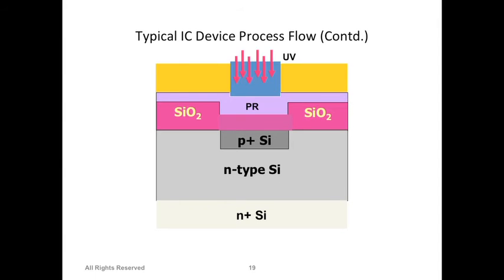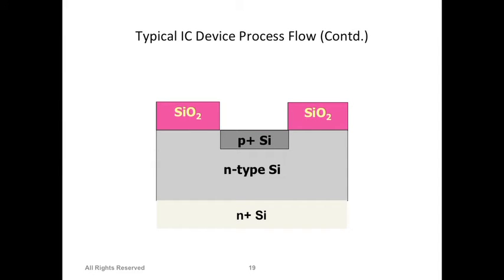Now, in this one, we want to make a connection here with gold, or any other metal, for example. Whenever you have a source, drain, and gate of any transistor, you have to address them with metal lines so that you can use them for your purpose, right? So you can apply voltage on them and turn them on and off. But how can we now use metal lines? We actually have to open up a small area.